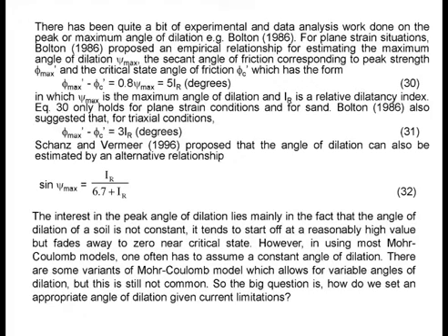Because the thing that is more obvious to you will be the peak angle of friction and the ultimate angle of friction, because that's what your triaxial test will directly give you. So if you can relate that to the angle of dilation, okay, I think that is sufficient for using the Mohr-Coulomb model. And this is really what it is. This is really the kind of thing that you need.